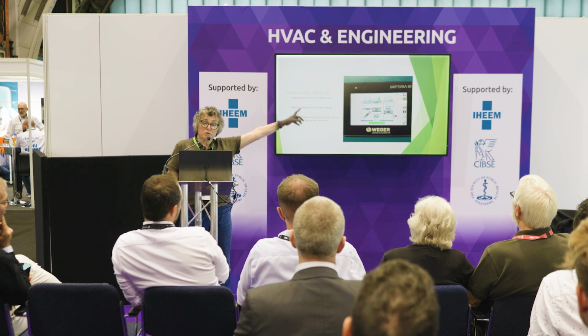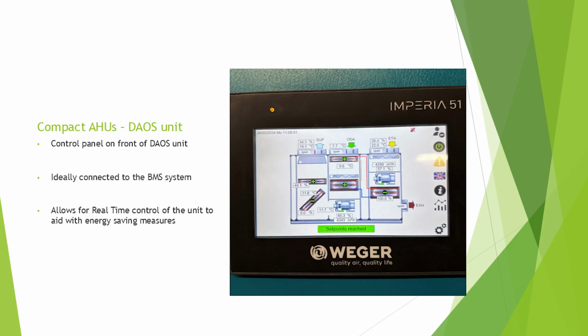And that's what the box on the front of that DRLC unit looks like. It shows you where the air comes in. I'll give you a minute to look at it. Where the heat recovery is. Intake fan, extract fan. You can see the air goes up and down as opposed to straight across.